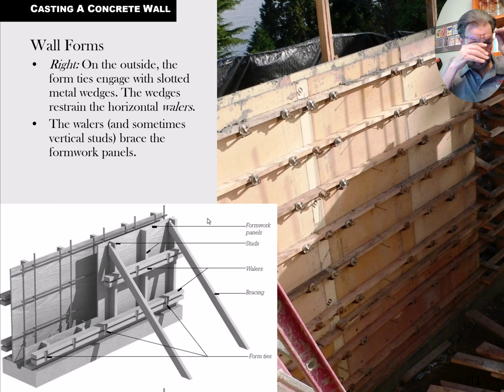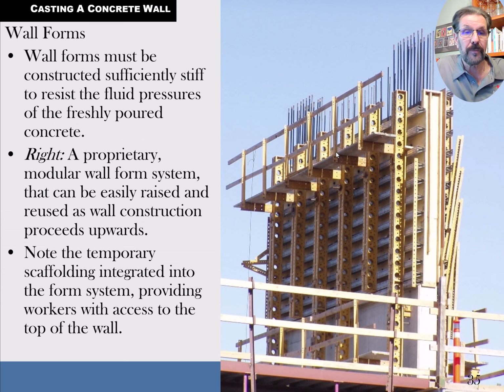They use that a lot of times in concrete slip forms, so that you can reclamp them to keep jacking up the forms and reclamping them against the existing concrete and pour some more concrete and keep going. Or sideways, if you didn't have enough forms to form the whole thing out, you might pour some of it and then reclamp it. And so that's a system that's used sometimes.